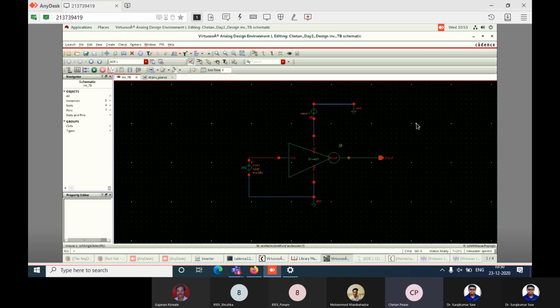And that will also contribute to the dynamic power dissipation, and that is 90% of the total power dissipation. That's switching. And similarly, this inverter is also having some output capacitances. When you study the RC model of a CMOS circuit, you can get the idea for that. So that power only we are calculating here. We are calculating the power, right? So we have done up to here.